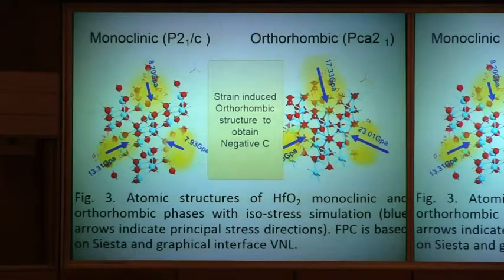We put tantalum nitride on top of hafnium oxide, and it induces a strain and induces the correct crystallization structure. So this strain engineering is key to making the orthorhombic crystal phase. So we use strain engineering. This is also the first time we use this principle to realize the right crystal structure like this.